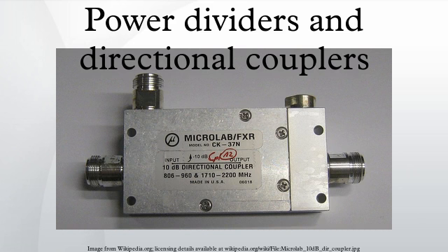Directional couplers are most frequently constructed from two coupled transmission lines set close enough together such that energy passing through one is coupled to the other. This technique is favored at the microwave frequencies where transmission line designs are commonly used to implement many circuit elements. However, lumped component devices are also possible at lower frequencies. Also at microwave frequencies, particularly the higher bands, waveguide designs can be used. Many of these waveguide couplers correspond to one of the conducting transmission line designs, but there are also types that are unique to waveguide.